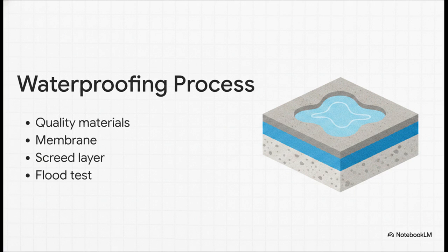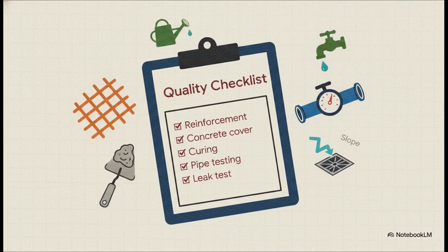But the real standout here? That last point, the flood test, also known as a ponding test. You literally fill the sunken area with water and just wait. You wait to see if it leaks. It's absolutely 100% mandatory. So the major takeaway here is this quality checklist.